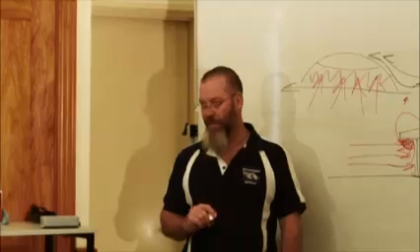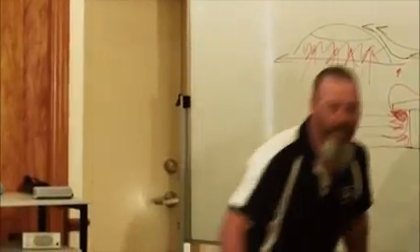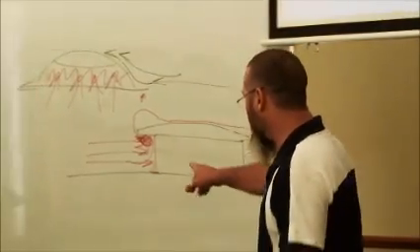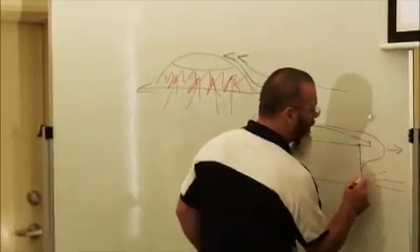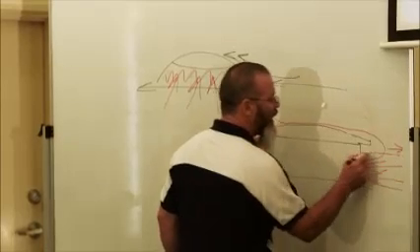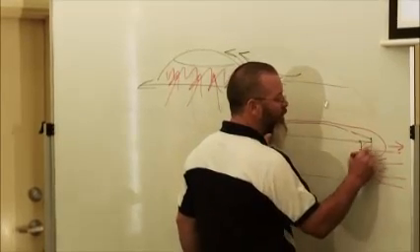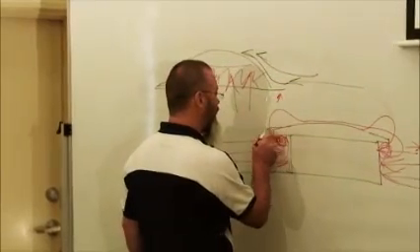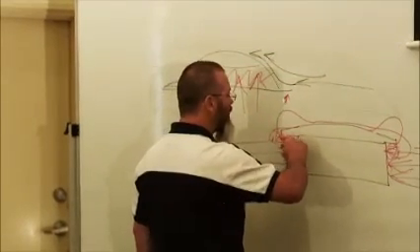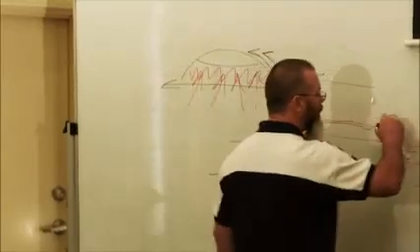There's only two wind directions. There's short side of the building, that way, and from the other end, that's one wind direction, and long side, so from this end and that end. So when you think about this one, wind comes from this way, you're also going to get wind coming from this way. So what you're going to end up with is another Bernoulli bubble where it all builds up here on this side, coming across, and around here you're going to get another one here. So you've got these vacuums here and here.